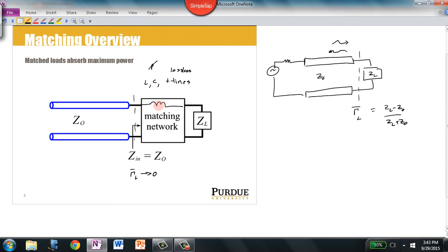While we could use physical capacitors and physical inductors in series with the load, this approach isn't actually ever really used in application. And the reason is twofold. The first is that the approach requires cutting a transmission line and soldering in a capacitor or an inductor in series, and that will obviously compromise the cable that we're using. The second is that at high frequency, physical components become less and less ideal as the parasitic effects begin to dominate their behavior.